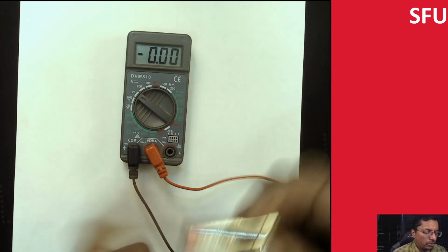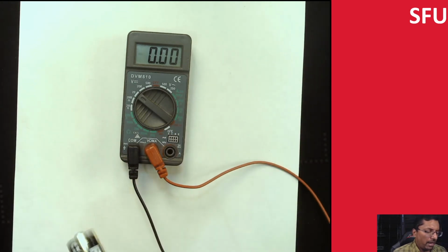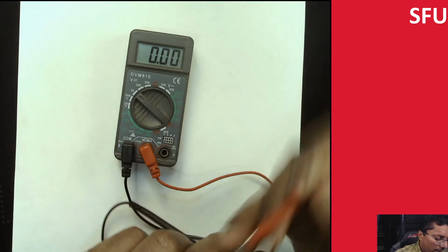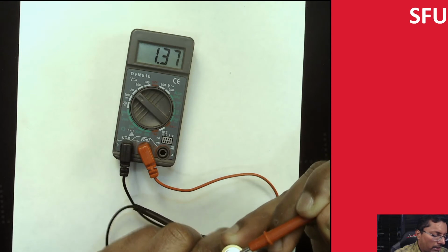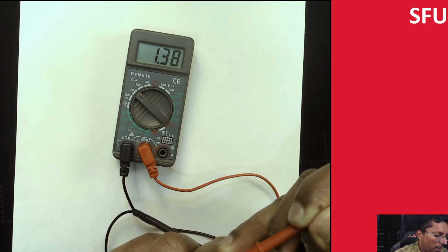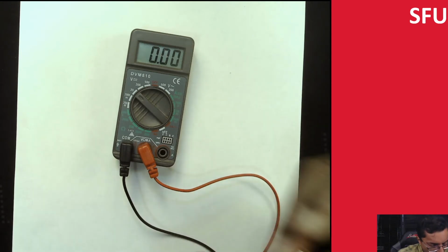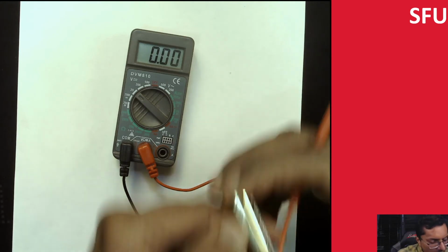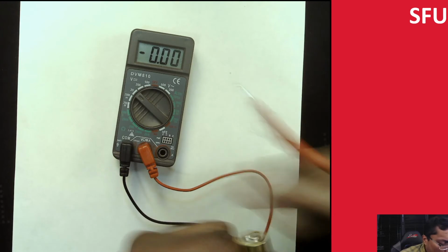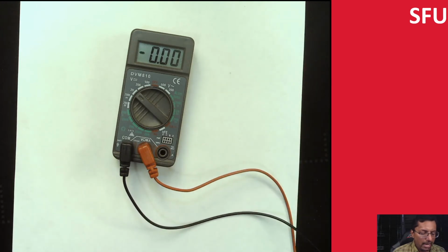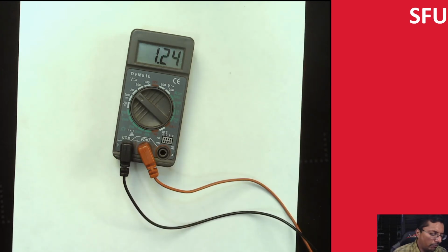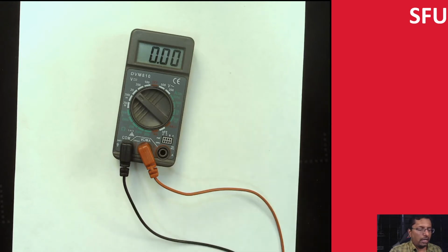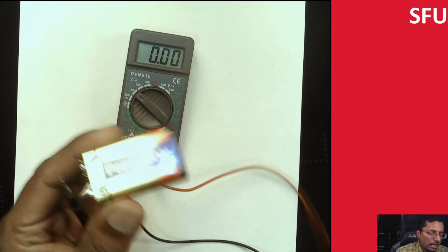What I typically do is, notice if I connect the black one, which is connected to the 0, and then I connect the red over here, it shows about 1.34 volts. And if you look at the battery, it gives you different standards, and it's supposed to be 1.5 volts. So this battery is probably a little bit dead. It's producing a little bit lower voltage. It's been slightly used. And then this one is what's known as a 9-volt battery.